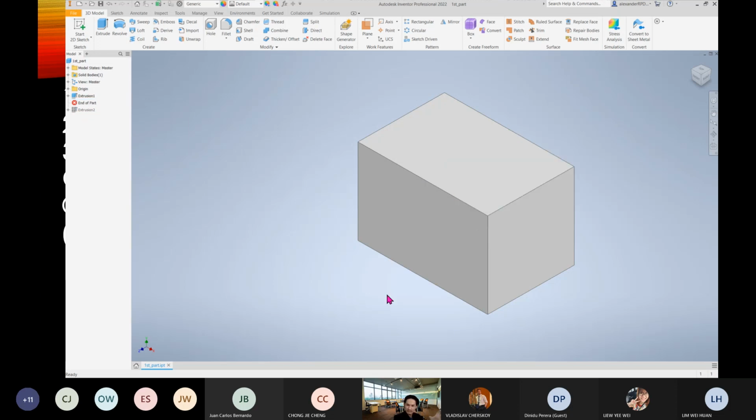And then after that, you do a milling, cutting. Now on your design tree, you have an end of part, right? So basically you can move this one on your features. Now I move this up to the beginning. So you know, we're seeing that people can read your modeling story.